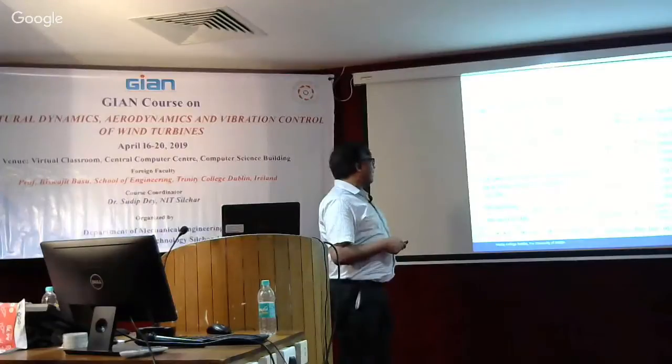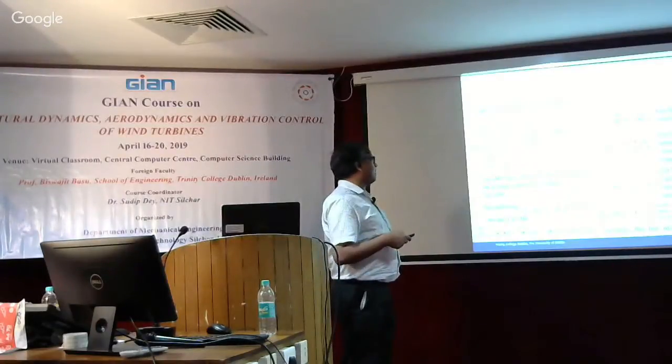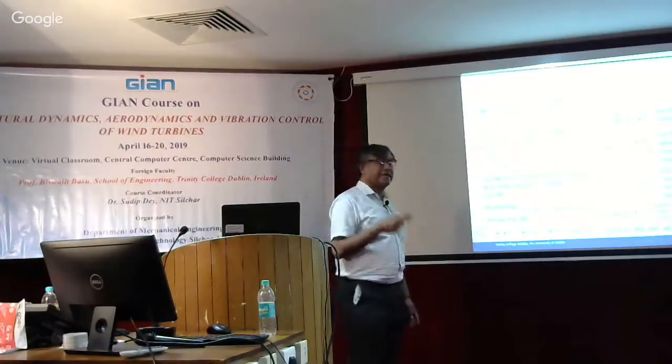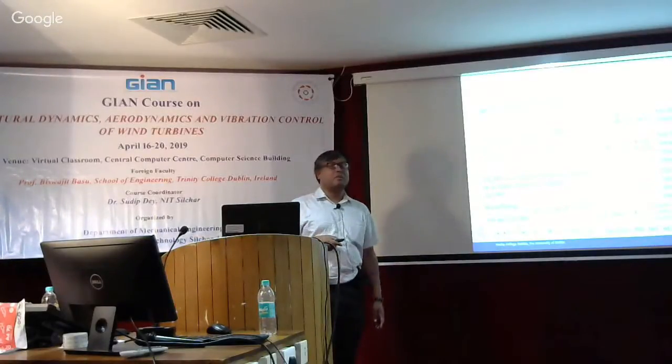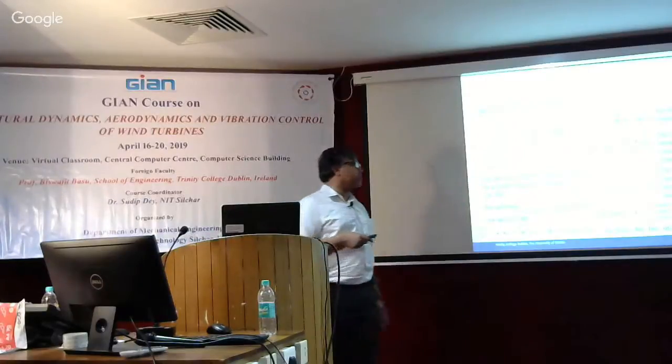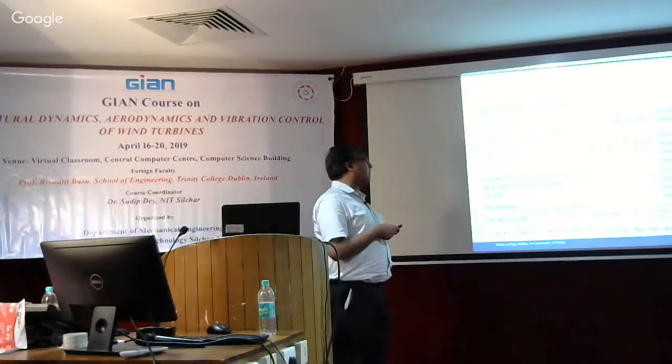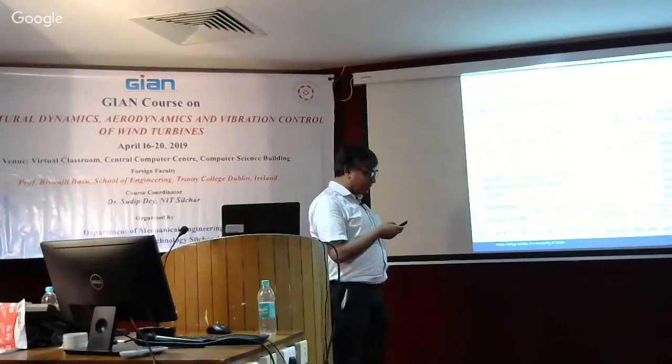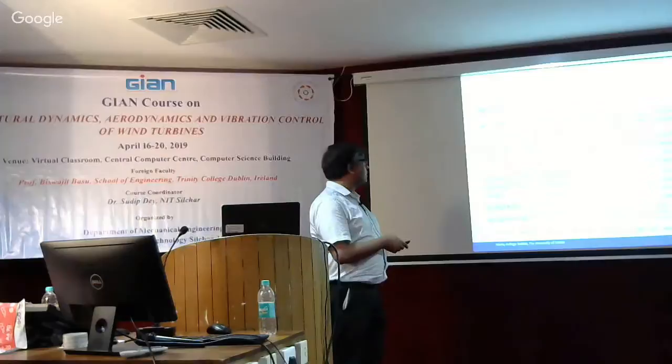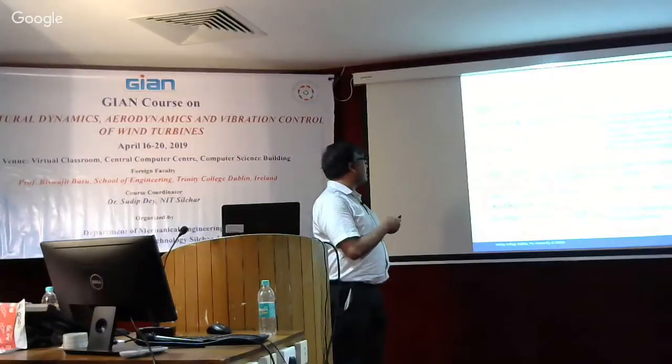So again, if we convert this to the non-rotating frame problem and solve the control problem, because we can do that in the non-rotating frame, once we get the control matrix, we have to then revert it back to the rotating frame. So what we do here is, this is the A matrix and this is U. This is a control matrix B, basically coming from 3 actuators of the 3 blades.